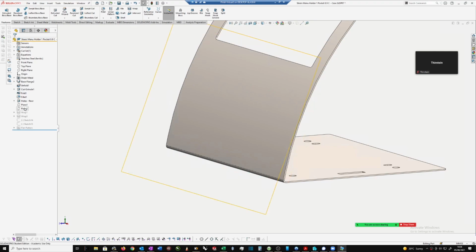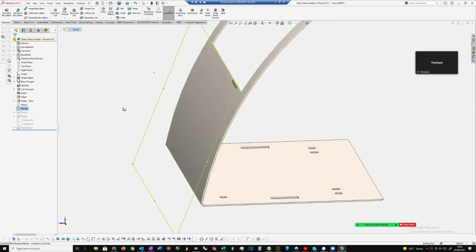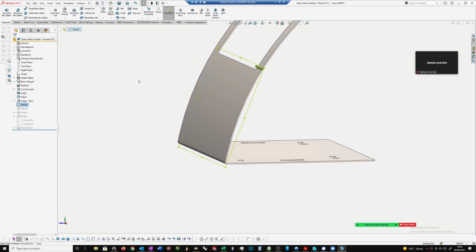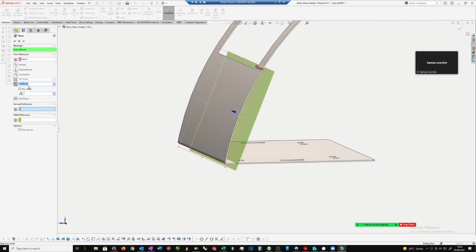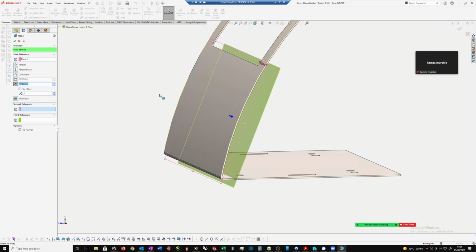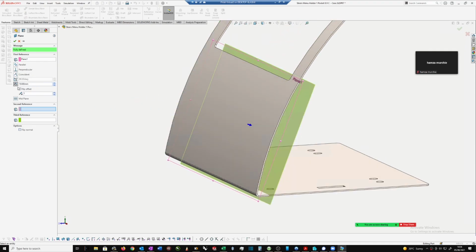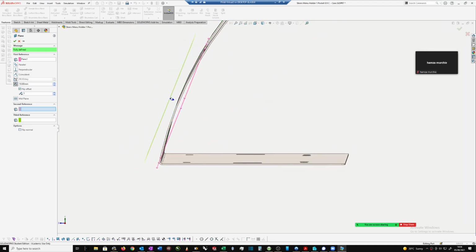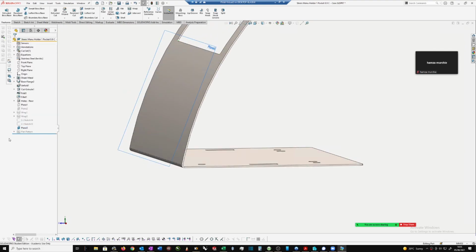Once I've done that, from that plane I've created a second plane which is just offset from it. All I've done is offset. Do you want me to explain how to do that? You can select the plane, go to plane, and it'll offset by 10 millimeters instantly if you selected something, and you can just flip it, like in this case I want to flip it. As long as it's offset by a certain amount, 10 millimeters or 5, it doesn't really matter. I say okay, and it's done.